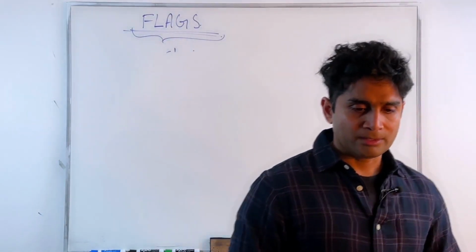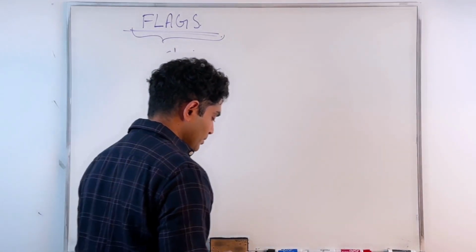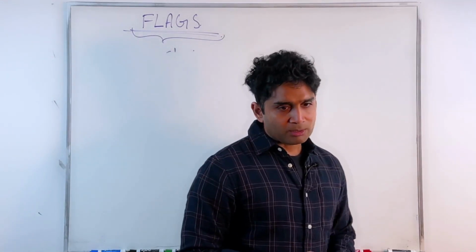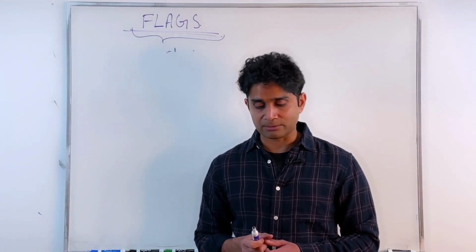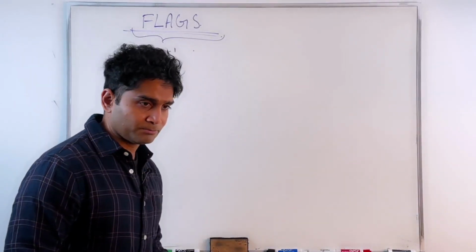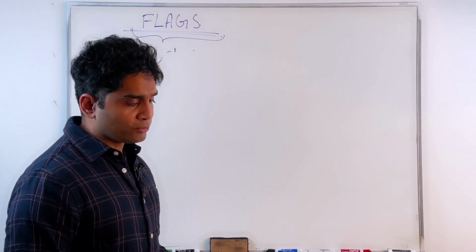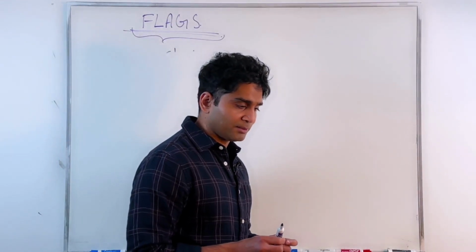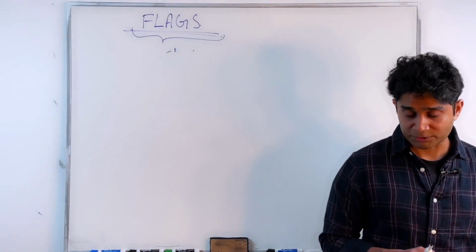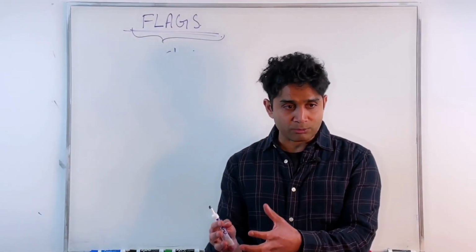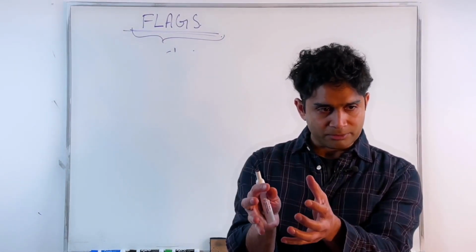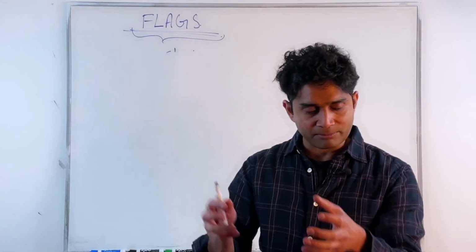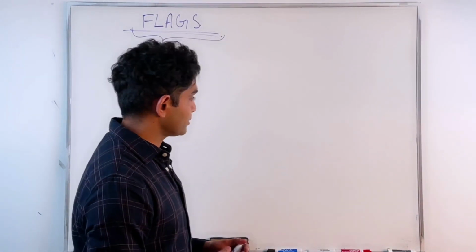B2Spice is one suggested program, but you can use other programs like Multisim, which is another program that can be used to simulate these kinds of circuits. B2Spice has a light version that you can use, but the university has a full version. I would recommend that you use the full version so that you can actually do it in a modular way. So you can create the simple circuits and convert them into a block, into a module, and you can use them as modules to build larger circuits.